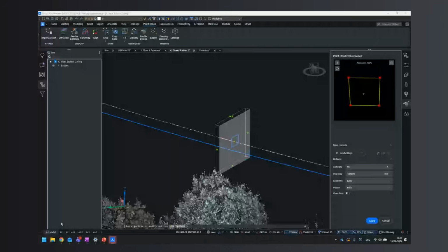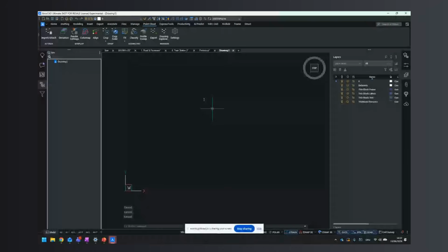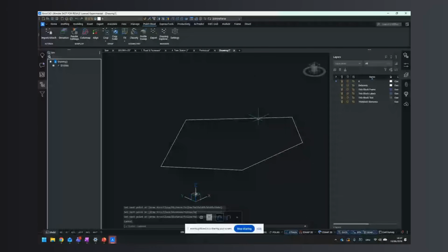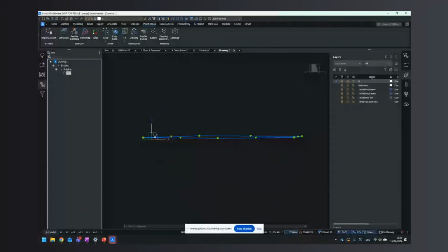You show the tools and methods available to elevate 2D polylines to 3D for site grading. Well, I need to share my screen again to elevate the 2D polylines and make them 3D. If you're working with 2D polylines, okay, let's do one. PL for polyline and C for close, right? This is a normal polyline. A 3D polyline means that not every point shares the same Z elevation. It means that all of a sudden one point goes right there.